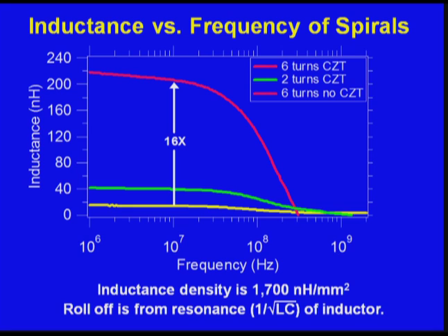In fact, the inductance was so much better, it was at 200 nanohenries, still not microhenries. Remember, the 1 megahertz inductors want microhenries, but it is 0.2 something microhenries. And in fact, this roll-off here is because of the RC time constant now. Now you've got capacitance from the wafer and so forth, and it's rolling off because of that, not because of eddy currents and other effects. It's not a materials issue, it's actually an electrical engineering issue that causes this roll-off. We've got so much inductance now that we have to contend with it as a circuit element.